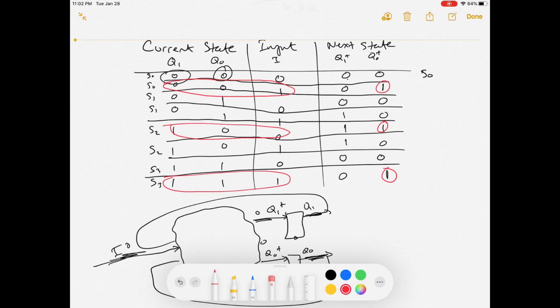When we say we want all these 3 inputs so that we output 1, it means this is an AND gate. We want all 3 of them to output 1. However, we want this or this one here to be able to output 1. So after we put these in AND gates, we're going to put all 3 of them in an OR gate, because only one of them is enough to output a 1.